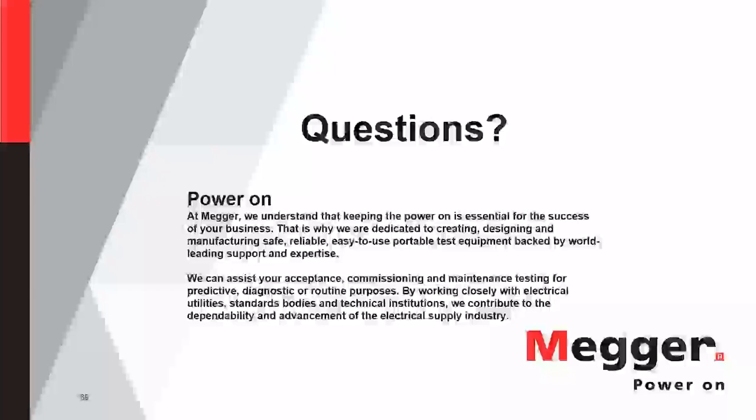So yeah, a couple of things. There's the calibration of the transducer that tells you pulses per degree, pulses per millimeter, or volts per millimeter, whatever. But then you'll hear the term conversion factor, you'll hear the term conversion table, or you'll hear the term transfer function. Like you'll look in the manufacturer's manual sometimes and they'll say the transfer function for this is, like I'll see one and it'll be a tangent function or a sine function.